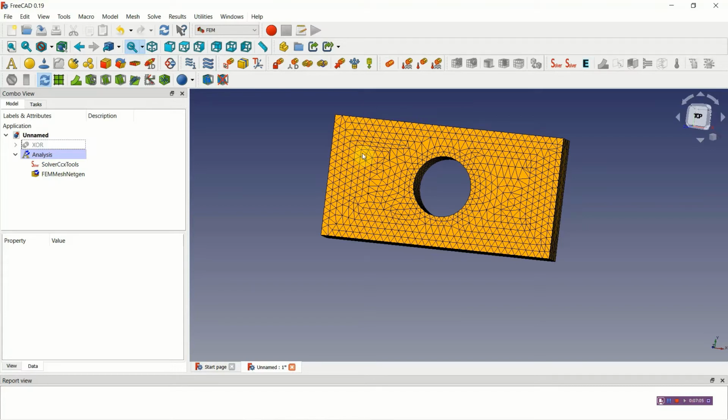And I'll assume this is part of a long structure. So this is a slice, if you like. So I won't define anything for this surface and the rear face. That means there will be no flow normal to these directions. If I define nothing, it is a natural boundary condition which will have 0 flow.